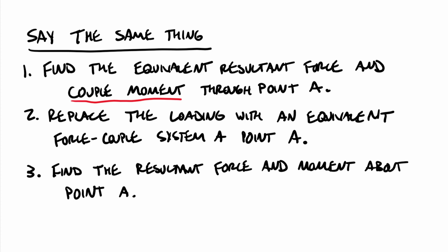Now, you may also see in some textbooks discussions about moving resultant forces to cancel resultant moments. To be honest, in my classes, I don't get into that topic because I think it's a dangerous idea of being able to get rid of moments. I know that all statics students would love to get rid of moments, so it gives you the idea you can get rid of moments in all cases, but it's a slippery slope. It's a dangerous idea. And so the language I'll try to use most consistently will be to find the resultant force and moment about a point. But once again, all three of these things are saying the same thing.